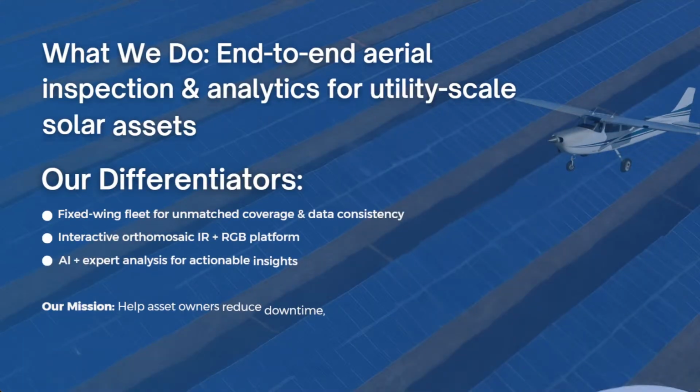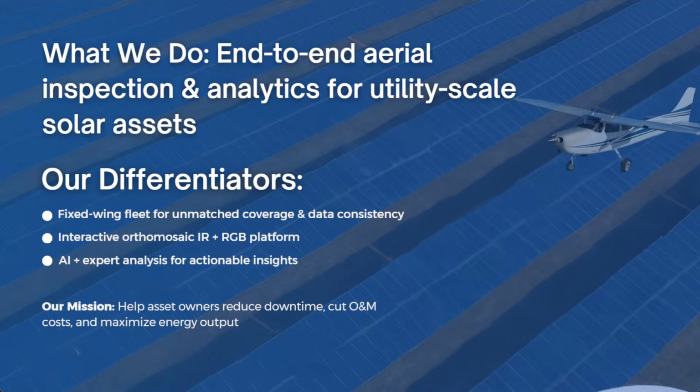So to really dive into it, what we do specifically is that we fly manned winged aircraft over utility scale solar sites, and we capture high resolution infrared and RGB images. Our equipment allows us to fly over sites and capture extremely detailed data on the panels with the infrared, so that way we can see things like hotspots or if strings are out. But also with the RGB camera, we're able to detect things like glass cracks.